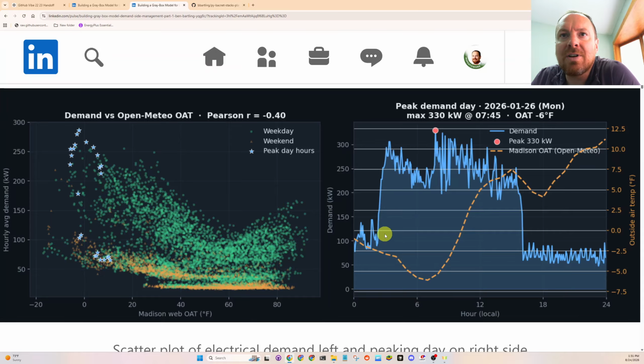The building started at about 3 a.m., the optimal start algorithm ran, and then school probably started around here. So this electrical usage right here was from optimal start warming up the building, and then plug loads and people pushed it up over 300, is what the submetering measured. So they do something with optimal start.